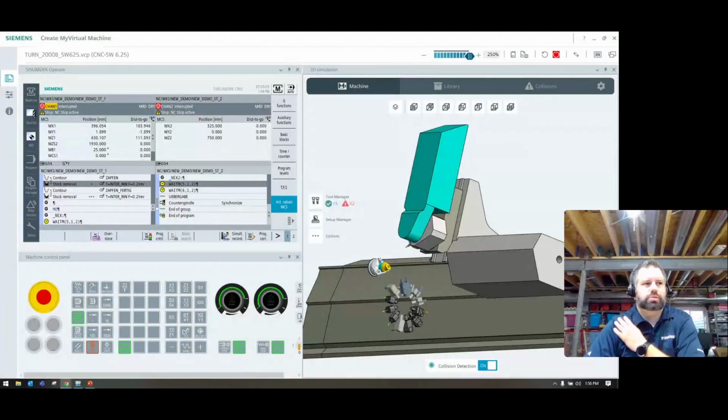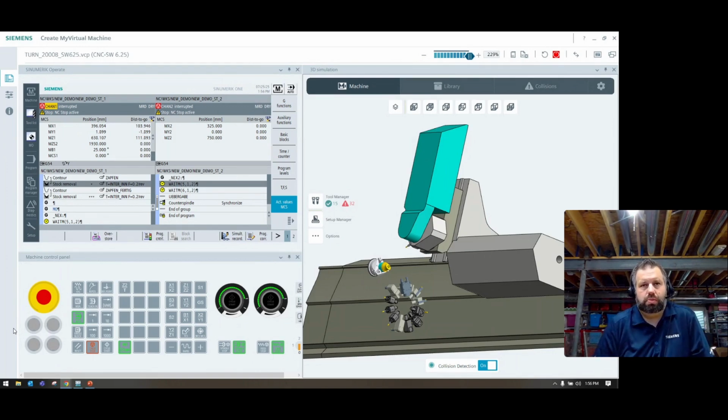But I would say you have more complex geometries that you need to have a turned finish on, or large geometries. I think that's really where it benefits. You want to get a better tolerance, a precision fit, go boring head for sure. It's going to be much more accurate because now you're relying on the positioning of the machine interpolating for accuracy. But great question. Thanks, Jesse.